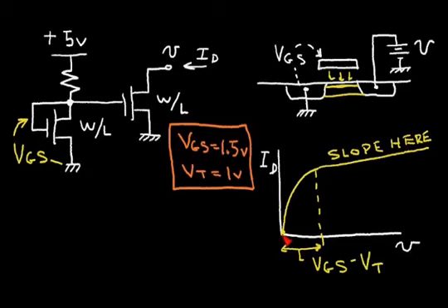And as I increase my drain voltage, I'll go up this curve, and I'll reach a point where it becomes relatively flat. It approximates a constant current, but not quite. And there's one important point, this point right here. This is the point at which it starts to become a fairly decent current source. And let's examine this particular point. I'm going to erase this channel region.